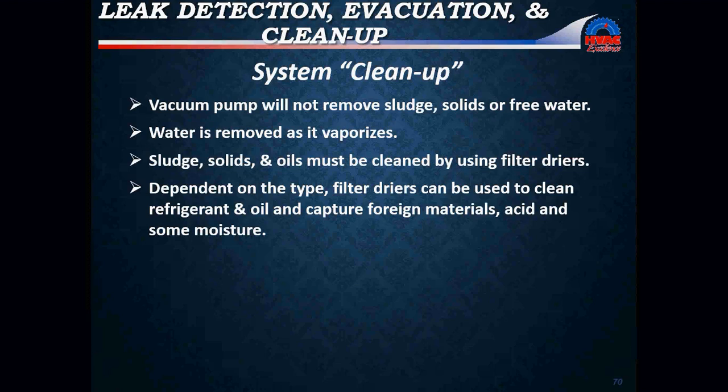Okay, when it comes to cleanup, vacuum pumps will not remove sludge, solid, or free water. Okay, water is removed as it vaporizes. Sludge, solids, and oils must be cleaned by using filter dryers. Depending on the type, filter dryers can be used to clean refrigerant and oil and capture foreign material, acids, and other types of moisture.